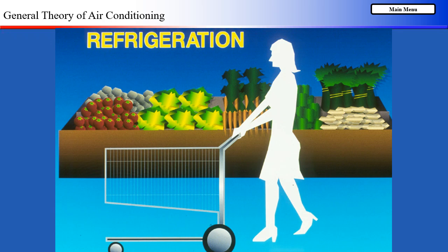Refrigeration refers to a mechanical refrigeration process to cool and freeze foods. It also involves the production of ice for commercial uses, such as ice rinks and ice storage. Grocery stores make extensive use of mechanical refrigeration. There we find coolers for dairy products, produce, and meats at about 35 to 45 degrees Fahrenheit, as well as freezers at -20 to +30 degrees Fahrenheit.